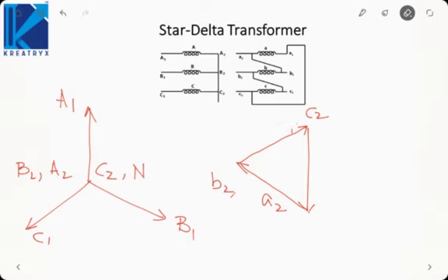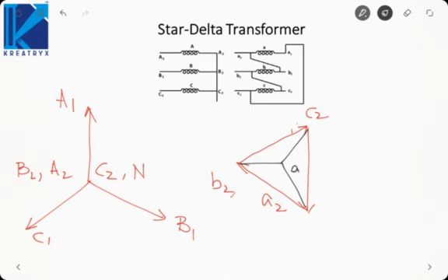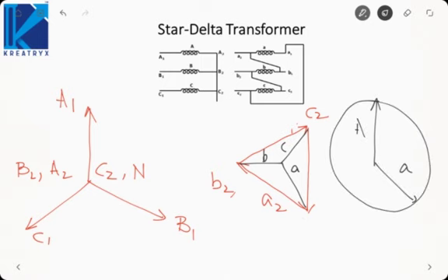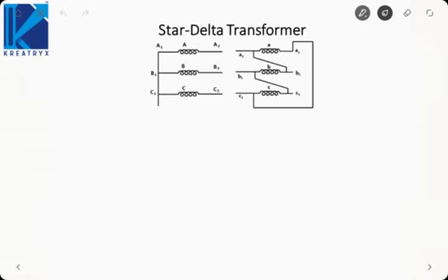Now we will need to draw the reference phasor. Okay. This is A, B, C. If we plot on a clock, capital A is like this, small a is like this. So this connection will be YD5. Okay, because it appears as if 5 o'clock is the time, so it will be YD5 type of connection. Now again let us change the primary connections. Now primary is like this.